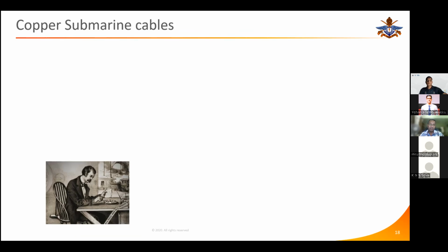I think I have answered that. As I said, in fiber optic cables, you can use anything between 850 nanometers to about 1700 nanometers. But the real usable part is between 1.53 and 1.57 micrometers. That is the part that we use in the undersea communication systems, because for one reason, that is the part of any optical cable that provides me with the lowest loss, lowest attenuation through the cable.